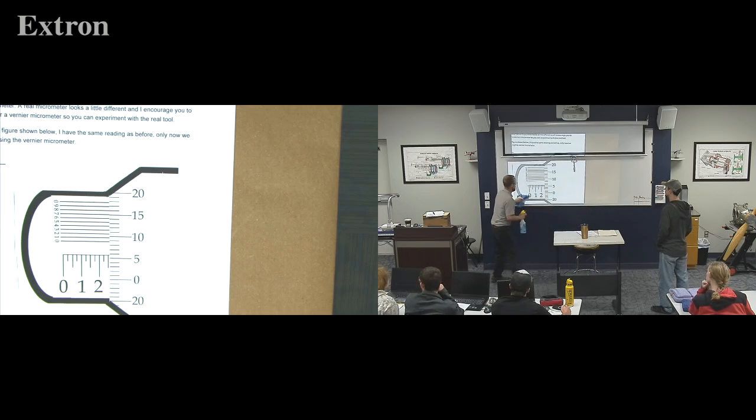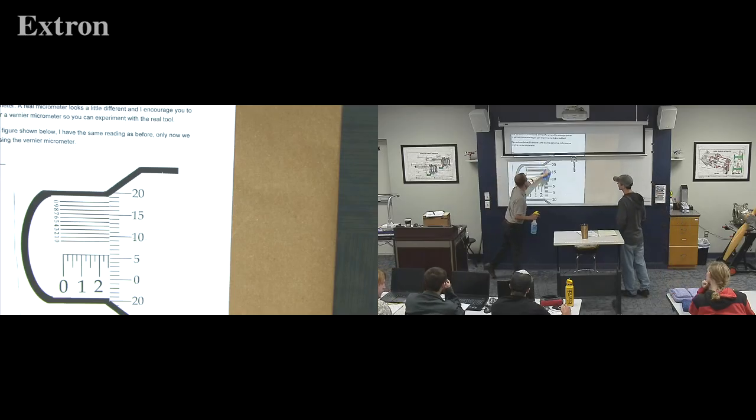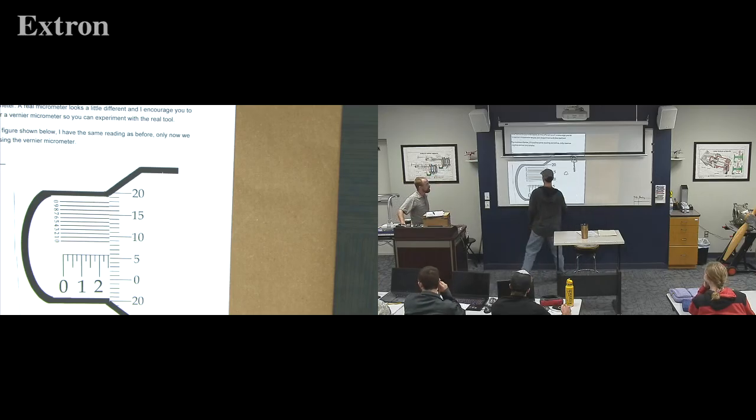All right. Show us. We said it's a 0 to 1 scale, so our first number is 0. Then it's past the 2, so the second number is 2. It's past the half. 0, 25, 50, so we have 5 at least. Then it's here past the 5, but not to the 6 yet, so our next one is also 5. And then the one that goes straight across is 8. So there's our number. Okay, all right, good job.